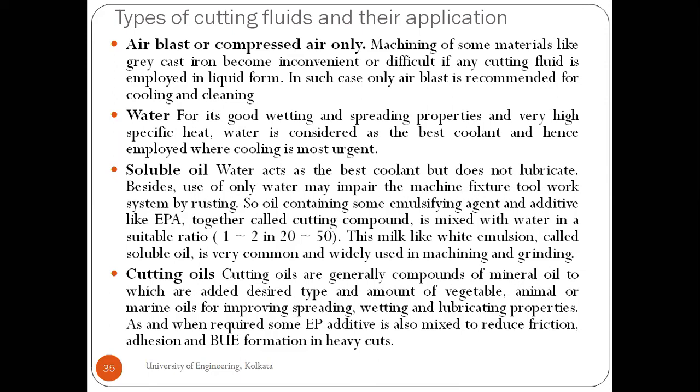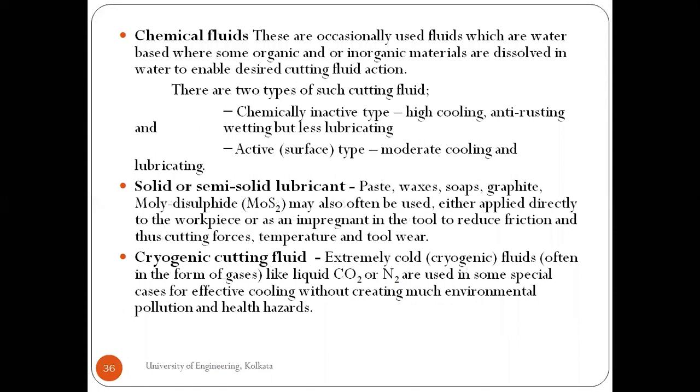We have discussed that built up edges are formed due to adhesion of the material. Chemical fluids which are water based, like some organic or inorganic materials, are dissolved into water to enable desired cutting fluid action. Like we can have high cooling, anti rusting, wetting, but less lubricating, in case of chemically inactive type of chemical fluids.